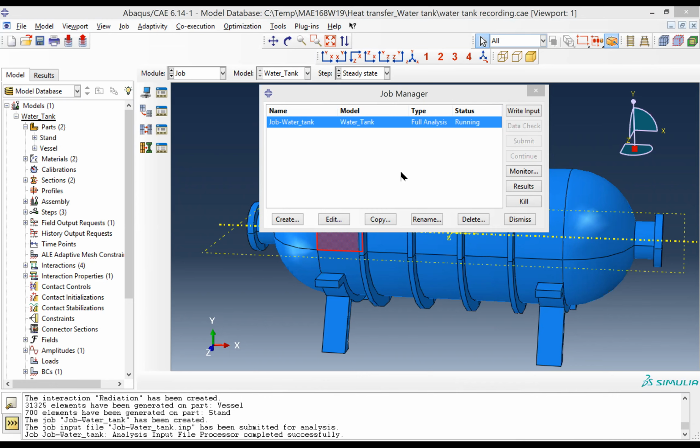For example, if we're doing some transient problem like this, it's important to follow the progress of the convergence at each step. So, for example, you can see here, let me see, what is the first step? Okay, let's take a look, for example, at step 2, first increment. Here's all the information, and it will tell you if the convergence has been achieved.